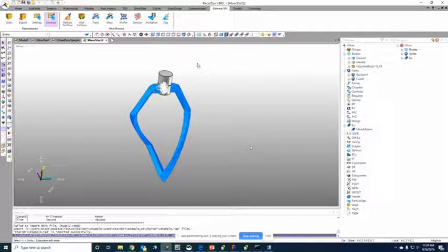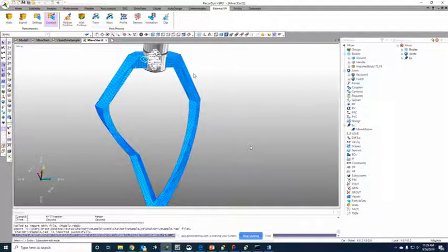Particleworks needs to know which geometry you're interested in coming in contact with the fluid, and for full flex bodies, you will need to define a patch set in order to define that body. Rather than sending the information about the body itself, it'll send the information about the patch set.